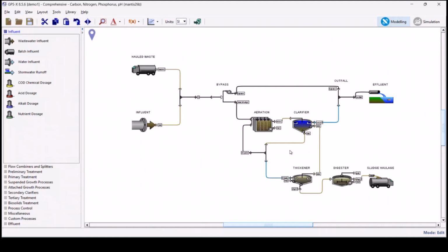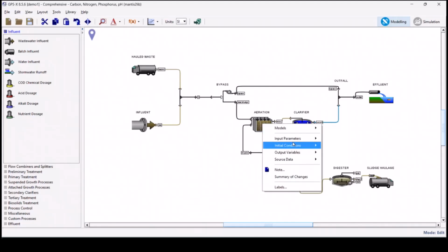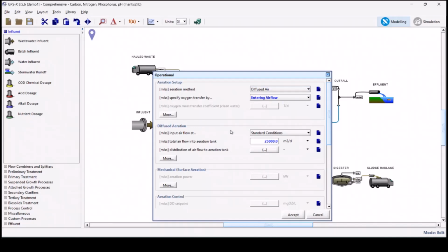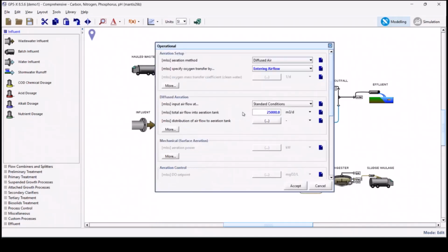And while we're on the topic of talking about those input parameters, one other thing that I do on a regular basis is, for any menu that you're going to open up, you may know that I need to often find the cryptic variable name for something. By cryptic, we're saying the actual variable that appears in the code, because if you are writing your own custom code or you're building a process controller where we ask you for the cryptic variable name of the variable that you're trying to control, those things you can find here by putting your cursor over there, and it pops up in a little window here.